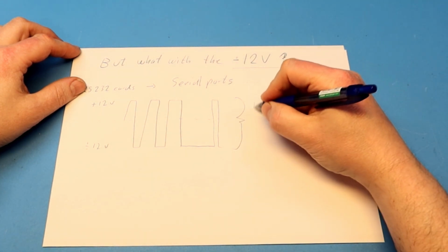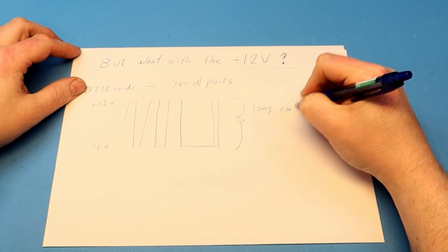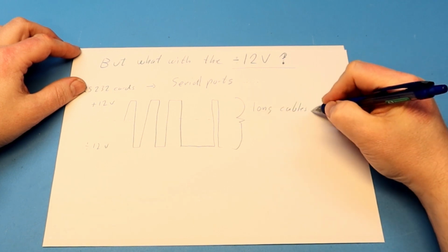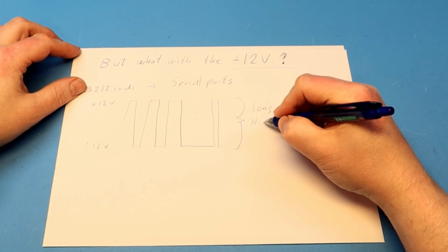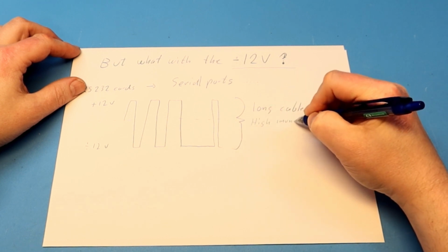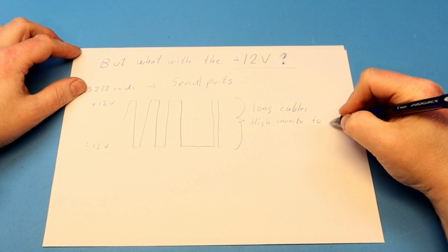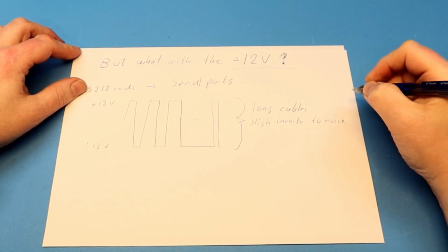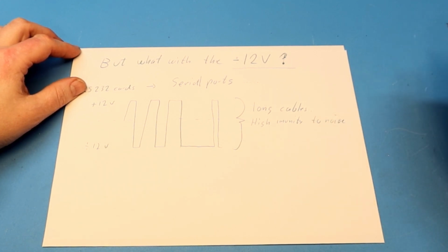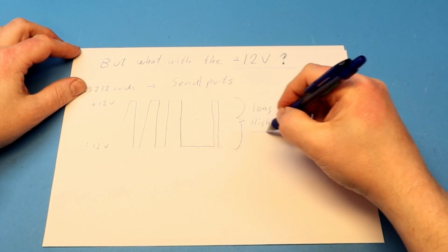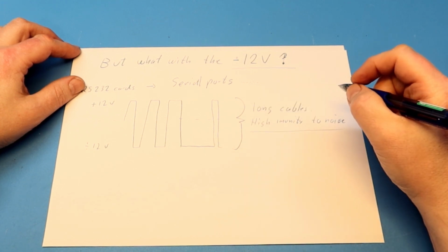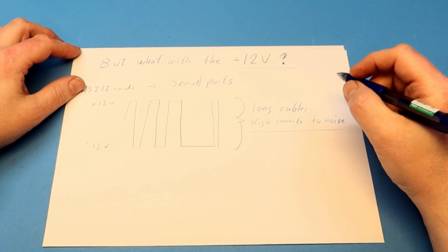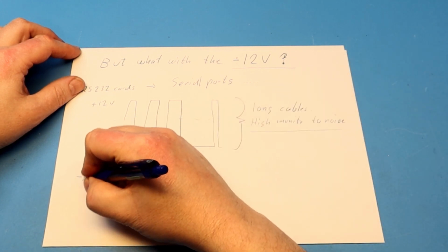And this is a factor that's also driven by the fact that we now have SSDs in the form of M.2 and PCI Express slots, where you don't have any power leads at all to run external equipment. And if you don't need 5 volt or 3.3 volt for hard drives or other stuff, it's no good idea to have the power supply them anyway.